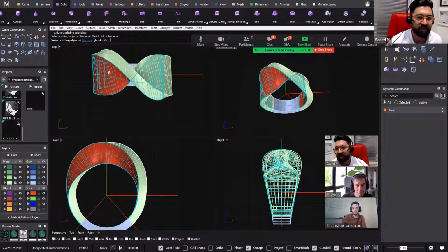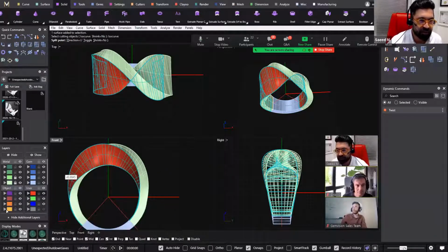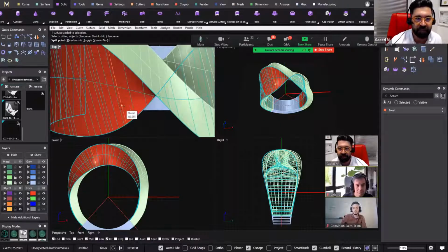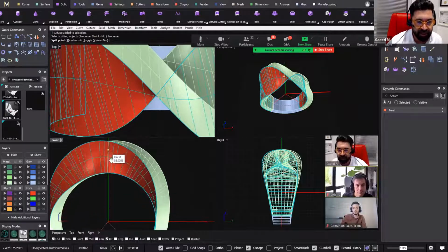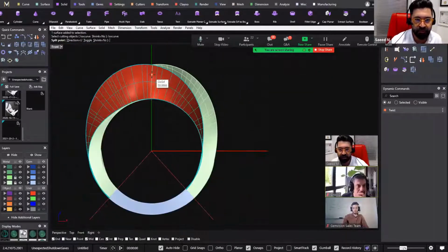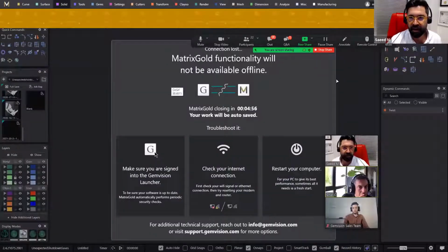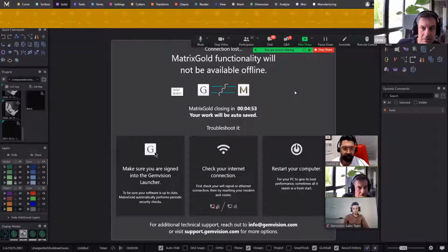So I click on the ISO curve, and I'm going to change the layer as well, so you can see the yellow ISO curve here. If this is a clock, here is 12 o'clock. I'm going to go from 12 o'clock to something near 1 o'clock here and click on split. Oops, I think this is the connection.